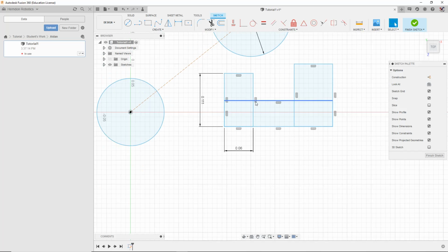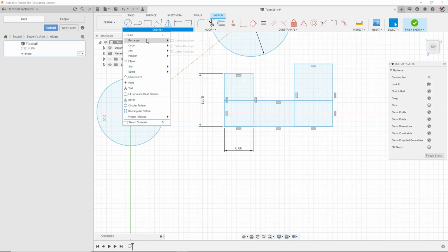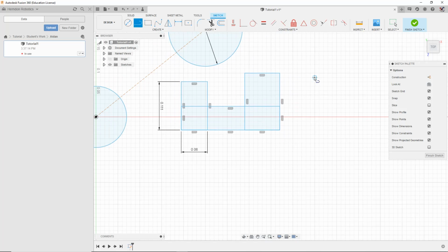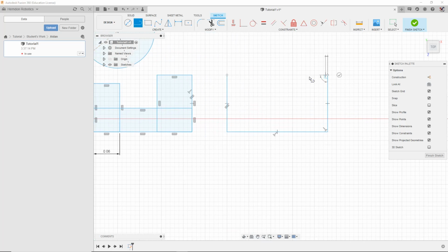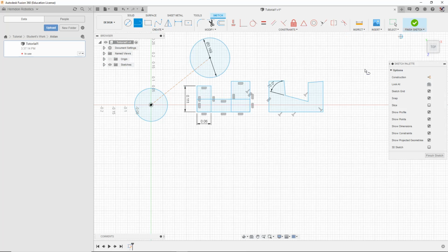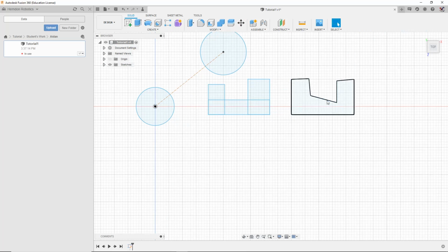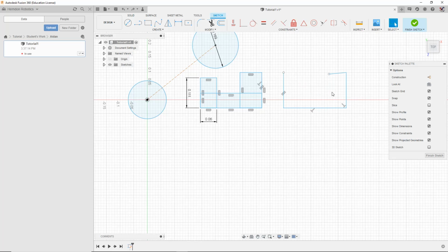The only problem is we have all these. And this is just where it gets a little bit annoying. Normally what I would have done for this is I would have just taken the line tool, and basically come like this, create a smiley face like this. I can even make it go at angles, and then angles relative to this I can change, because 40 degrees, 70 degrees, let's do this, and now we have that smiley face. And now this is just one solid shape, which makes it a little bit easier in the end. However, I'm just going to delete that for now.